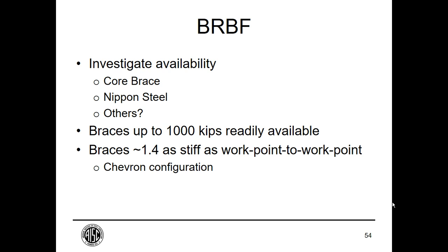We are using a chevron configuration. That's the upside down V, in a 30-foot bay frame. Actually, we're using it in the 25-foot bay frame. The manufacturers do publish literature, and I found literature covering the 30-foot bay. So I could give the manufacturer a call. In fact, I will cover this in some detail in live session 4. But for preliminary purposes, I'm going to assume a factor of 1.4, assuming the 25-foot bay is pretty similar to the 30-foot bay.